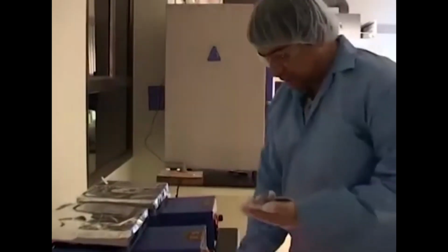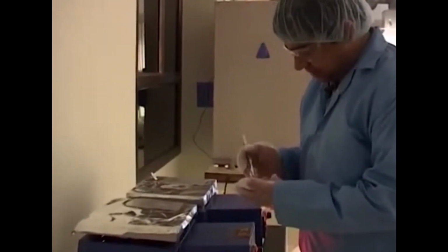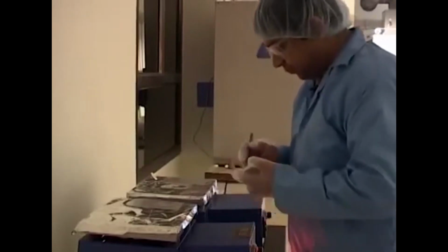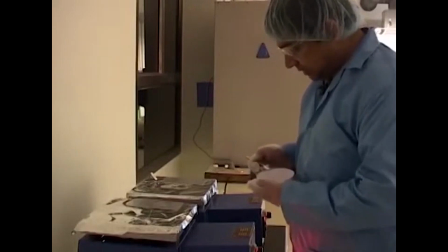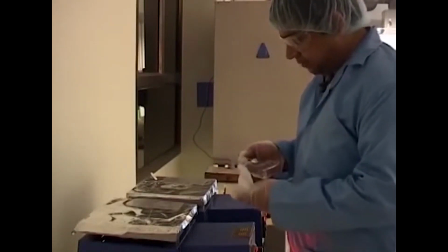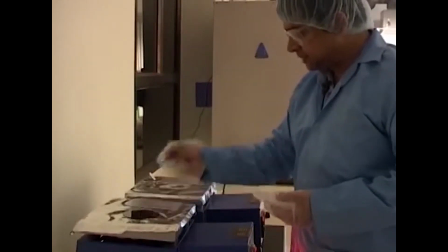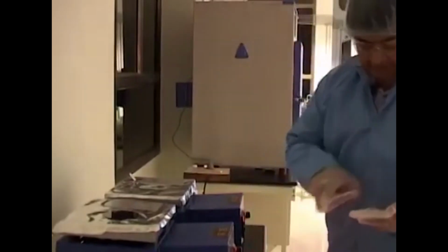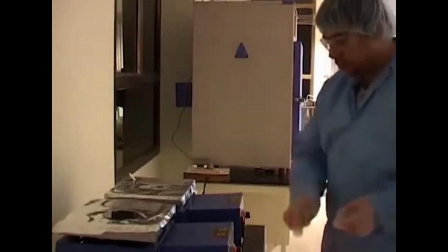So I'm going to now actually pull out this exposed wafer coated with photoresist as we did in the last step, and slowly put it on the top of this hot plate. And the time here that we give for allow it to be heated at the 65 degrees step is about 1 minute. We turn on the stop clock and essentially wait for the alarm bell to go in, so that we know that we have heated for the time cycle that was supposed to be.